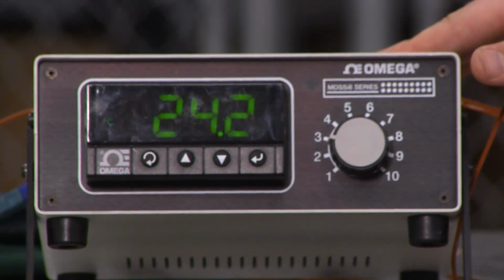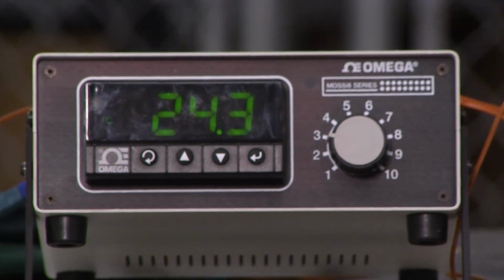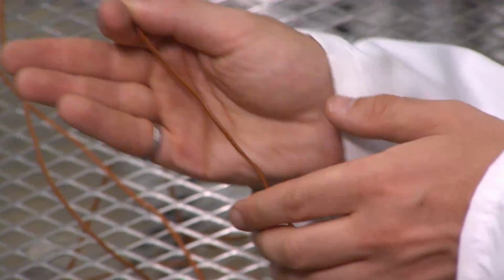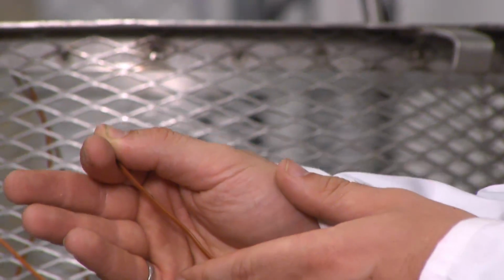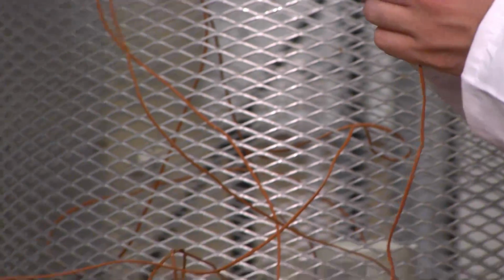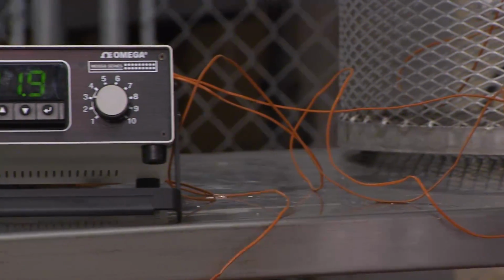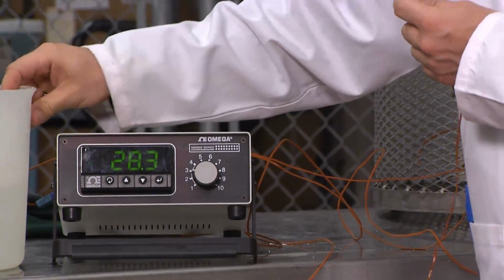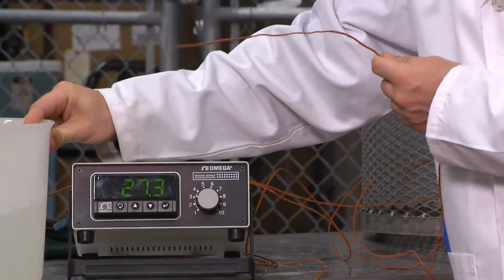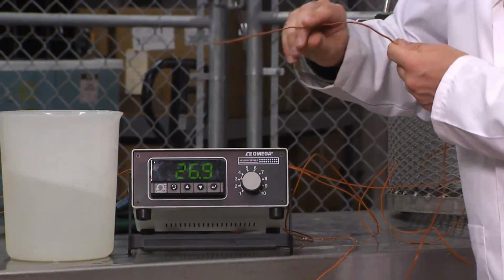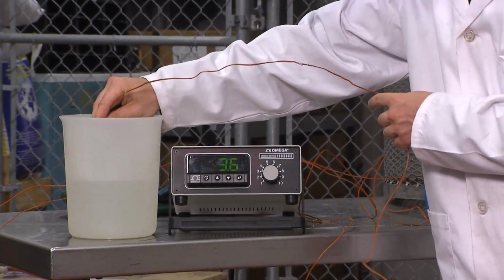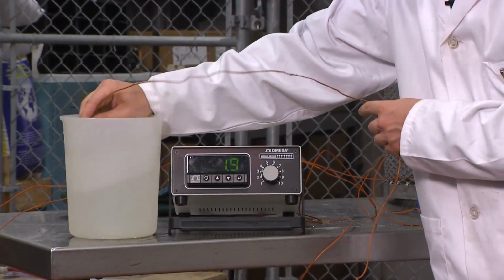You can check to make sure that the thermocouple is operating correctly by simply holding it to your skin, which in my case comes out at about 32 degrees Celsius, blowing on it, or submersing in ice water. Now, during the calibration, you'll be doing a 2-point calibration between a bucket of ice water, provided here, which, as discussed upstairs, should give you a temperature of exactly 0.